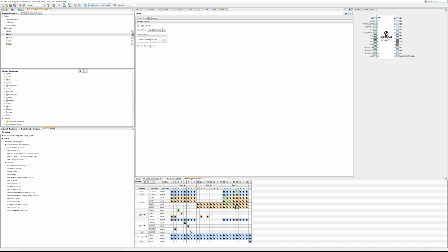You can use unity gain configuration, which will actually deselect the negative input. So now it is just a simple buffer. Whatever voltage you put in on the plus input, you'll get out on the output, but decoupled. So again, very powerful, just simplifies a lot of work. You can cut out a decent chunk of your circuit by utilizing these 2 op amp modules and not needing discrete circuitry to handle it.